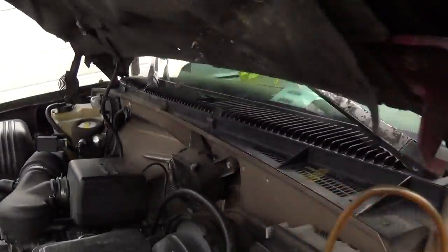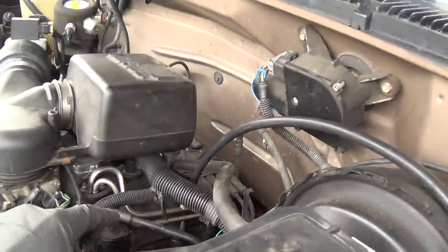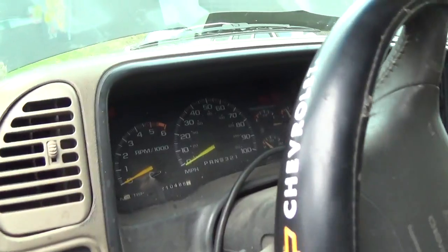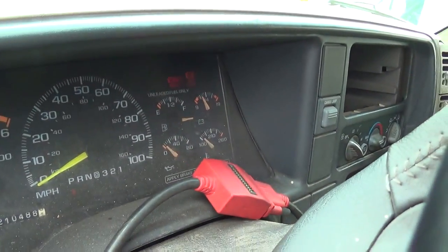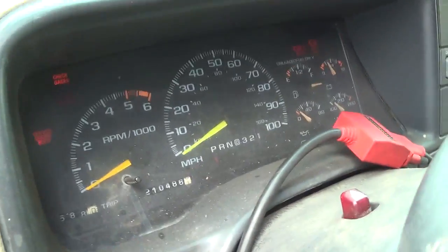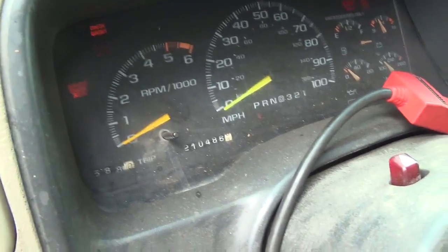Actually, not quite done. We have to remember the basics, guys. Fuel pump runs, there's no fuel pressure, like zero. Okay, and I squeezed the Schrader valve and a little fuel did come out of there. But judging by the fuel gauge on here, you know, it's always like it's off the chart. So maybe the owner just doesn't know how much fuel is in here. Is that a variable?